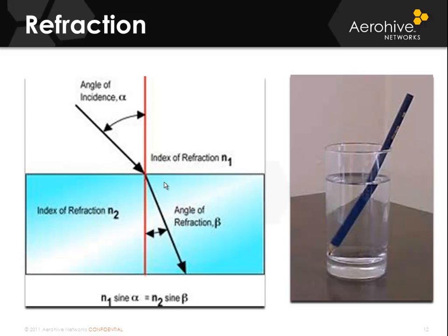Refraction. Refraction is when the signal is changed in direction due to passing through a different type of medium. A good definition of this is the bending of a signal as it passes through a medium with a different density, causing a redirection of the wave to change. The RF refraction most commonly occurs as a result of some atmospheric condition. The three most common causes of refraction are water vapor, changes in air temperature, and changes in air pressure.